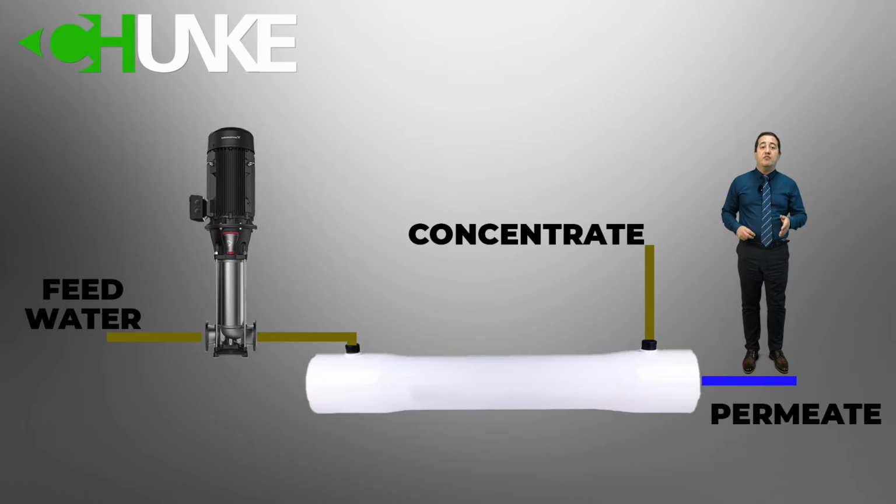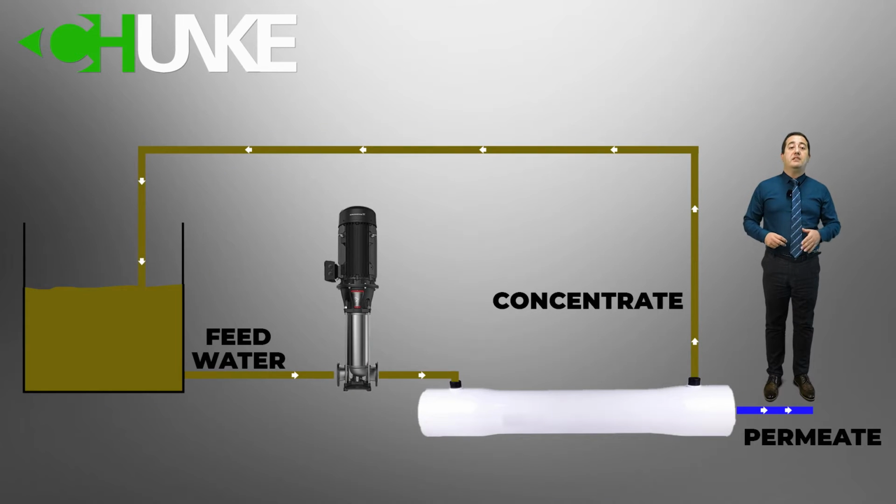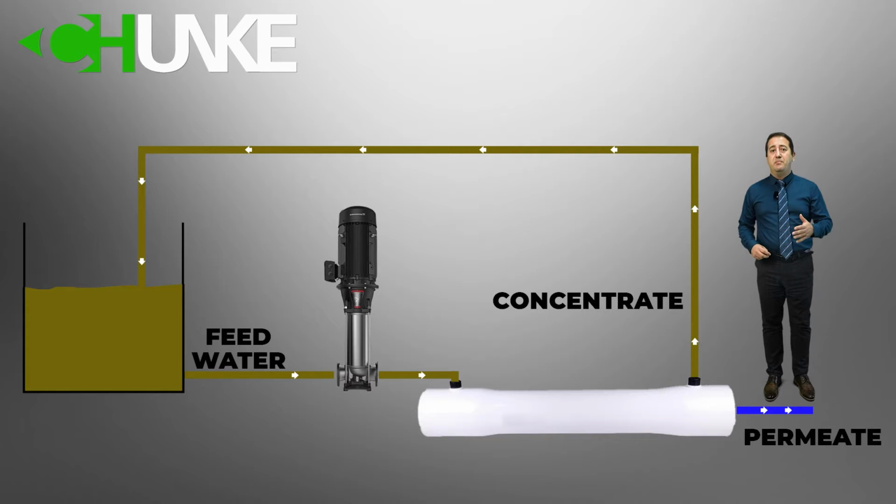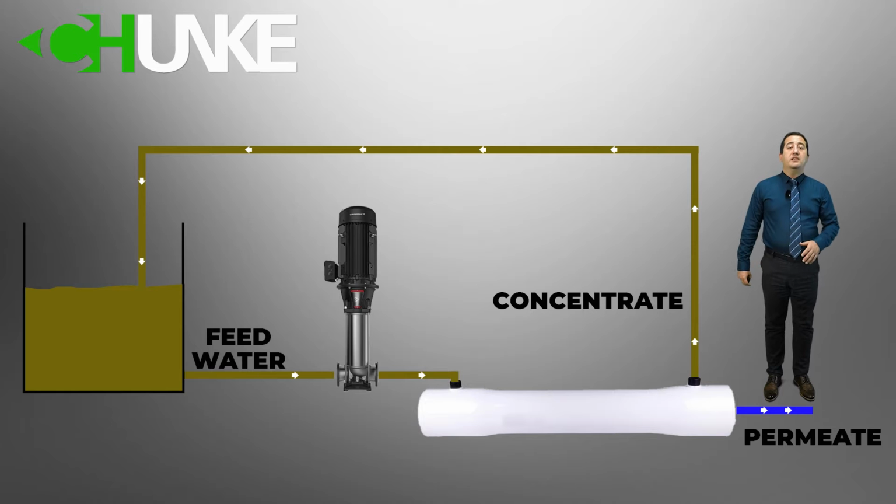But sometimes, if possible, to increase permeate quality and efficiency in all systems, we send concentrated water back to the feed water source. This flow type is concentrate recirculation. It depends on concentrated water TDS level, membrane recovery rate, and membrane type. Here you can see the concentrate water recirculation type reverse osmosis system diagram. Determining the flow type needs experience and technical knowledge.